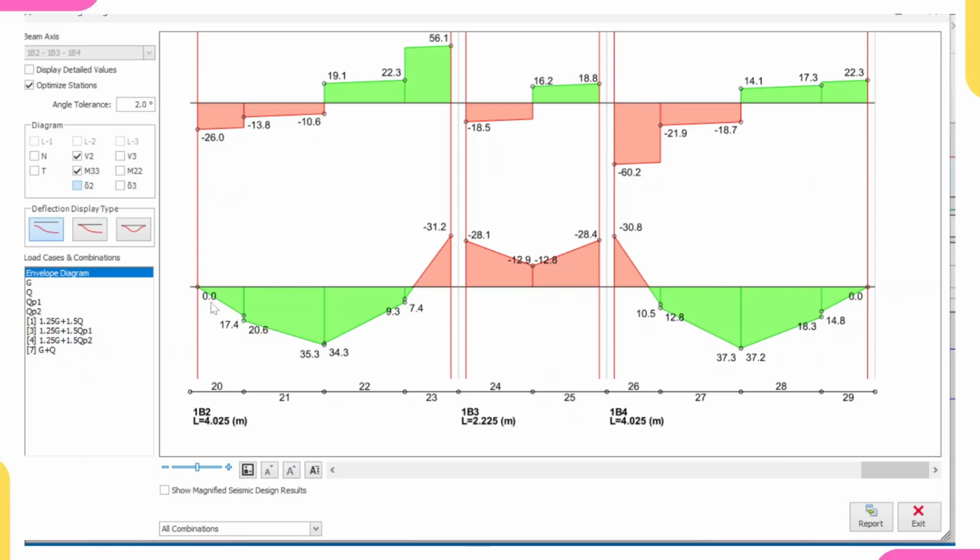And then in design, ProtaStructure will provide reinforcement to counter this moment. If it provides reinforcement to counter this moment, that means you'll be over designing, and you are no longer economical in your design. So this is the reason why I say you must hinge your member so that it will start from 0. We hinge there and we hinge there, so that's why it starts from 0.